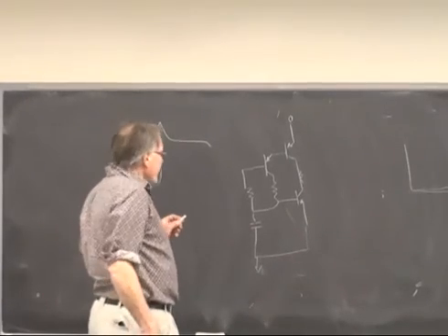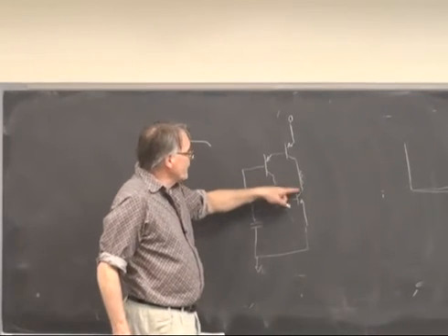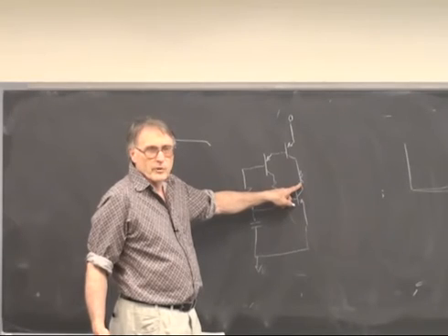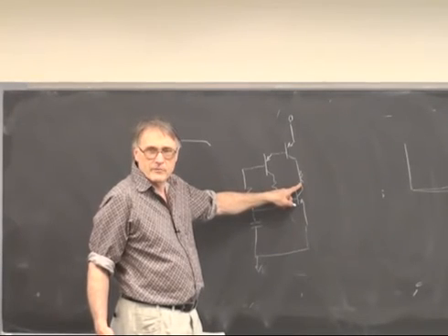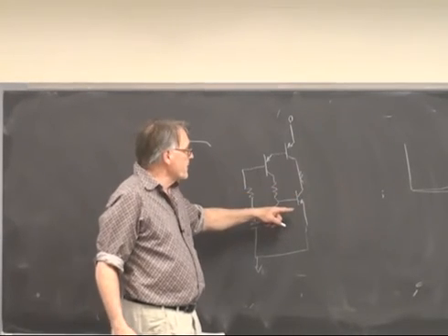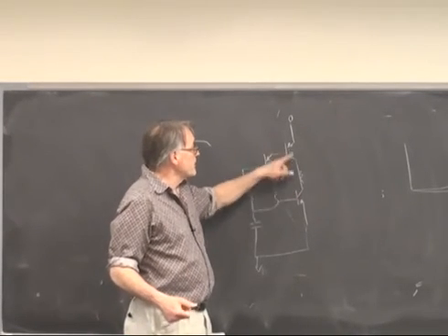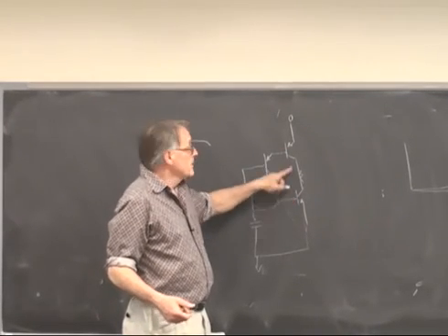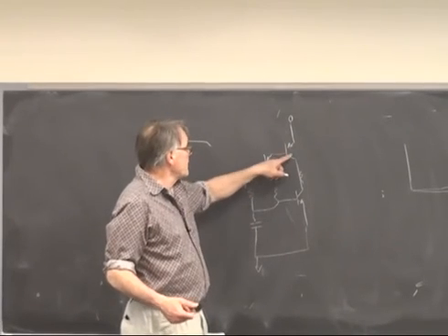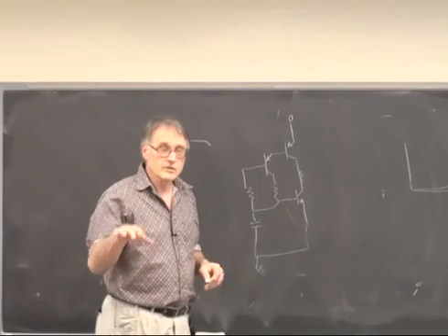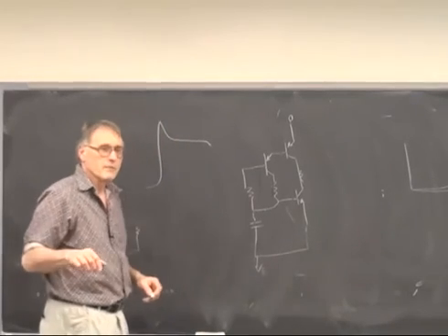And so the effect is to regulate the voltage here at 2.0, or 2.1 or 2.2 volts, something in that region. If it's lower than that, no current flows. If it's higher than that, these transistors are forward biased and more current flows. So it's a 2.1 volt regulator.